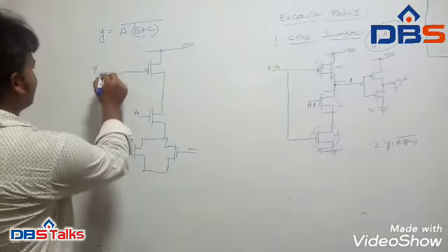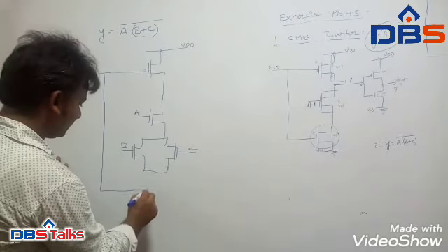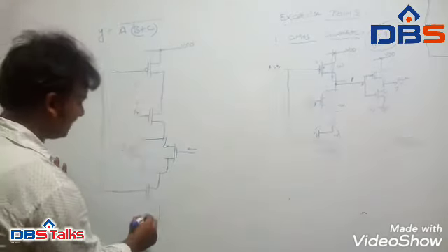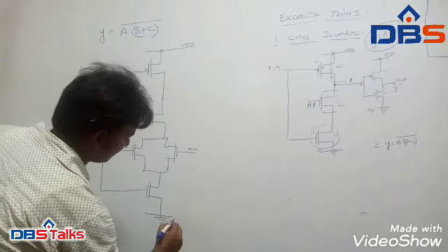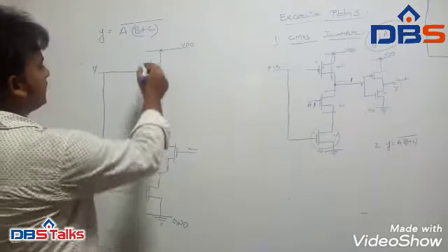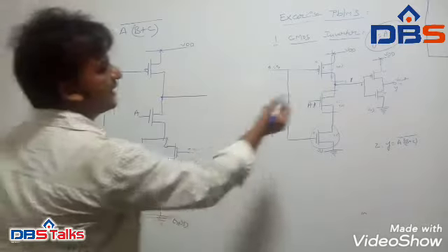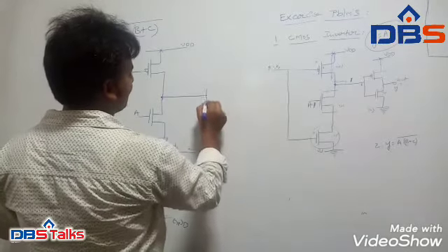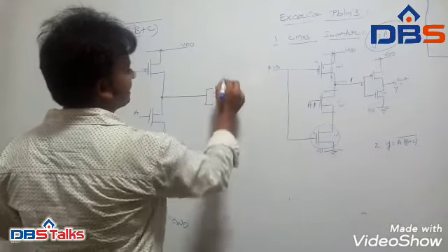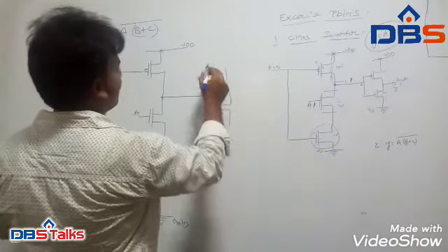Again I have to take a transistor for the evaluation mode, which will be in series with the entire setup, and finally that will be connected to ground. Here, in between the evaluation and the pre-charge, wherever the NMOS logic is present, we have to connect a CMOS inverter, which consists of both a PMOS transistor and an NMOS transistor.